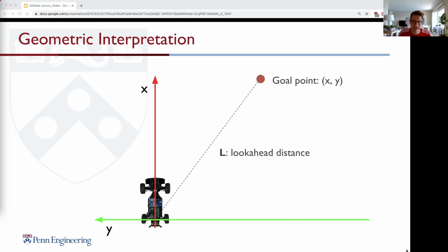But here's one thing. Our autonomous vehicle is a robot that is so-called non-holonomic. You can look up the definition, but more or less it means that the car cannot move to any point directly. It has a certain path it needs to follow. This is because of the steering. You know that the car has a steering where both of the tires move, like the front axle steering, and this is called Ackermann steering.